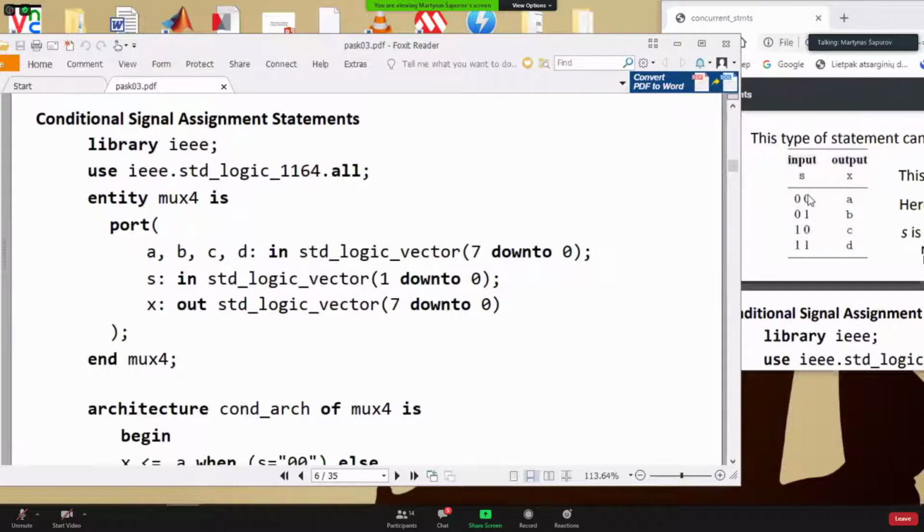Depending on the addressing input, which is our control input, our multiplexer connects any of the preferred inputs, A, B, C, or D, to our output X. To make it more logical, all our inputs A, B, C, D, and output X are 8-bit, 1-byte signals.